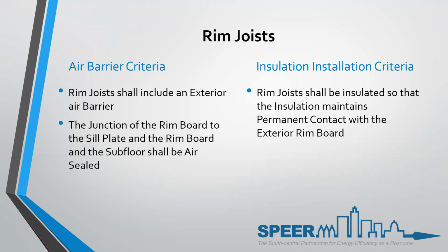Defects in the air barrier and insulation system can cause heat loss through floors over unconditioned basements and vented crawl spaces. So this results in higher energy costs and uncomfortable cold floors. Air sealing and insulating the band and rim also helps create a complete and continuous air barrier. As we said before, you don't want a misalignment of the thermal envelope, so you're going to include an exterior and interior air barrier along with insulation in between.